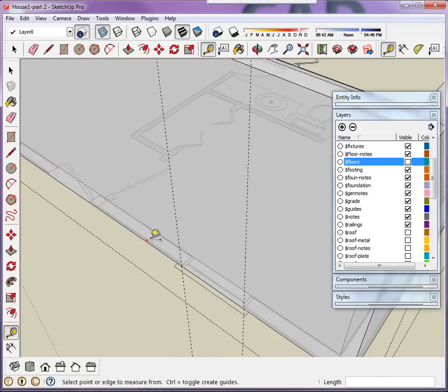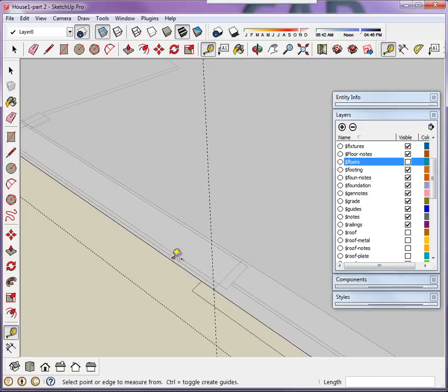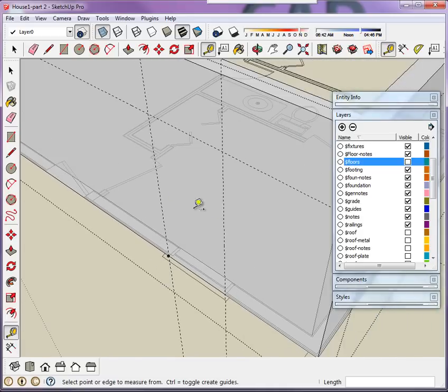Now as you zoom away, also you want to make sure that you're snapping not to these interior lines, but to the exterior face. And you're going to pull another guide up along the z-axis. All right, type in 6 feet 8 and then enter. So this shows you the left-right boundaries. Here's the top boundary. From this top boundary, you're going to create another guide straight down, and I believe this is 5 feet. So this here represents the general size of most of the windows, right?